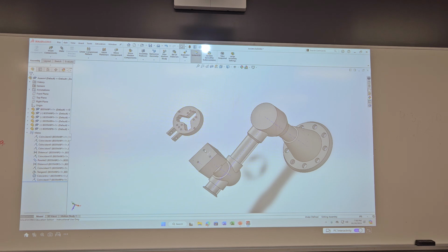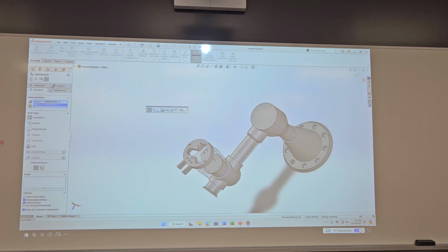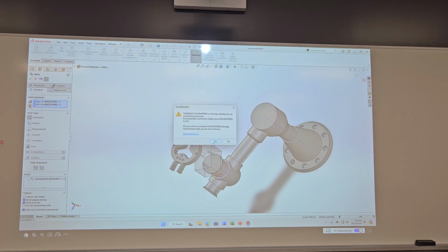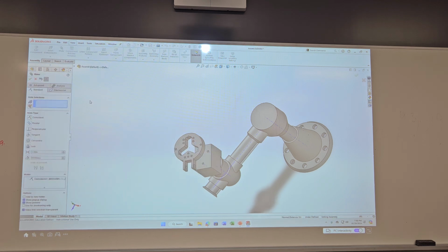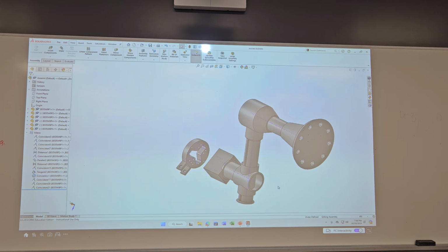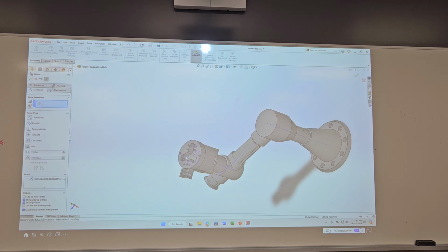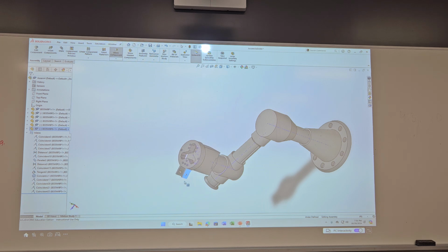Okay, now we have to make the bolts. So if you look at these bolt holes, 1, 2, 3, these are mating with bolt holes 1, 2, and 3. Okay, so let's make them axes. First one, so it can still rotate. Second. Okay, so now it cannot move. And the last one, this face to this face. Okay, so the block should move relative to the fixture.